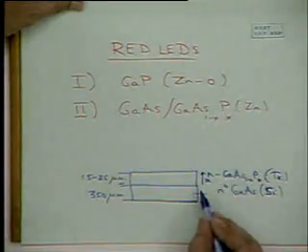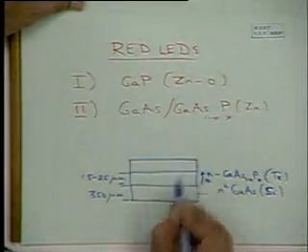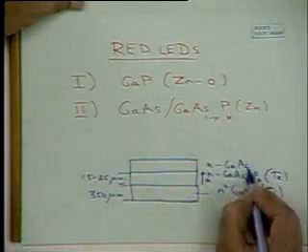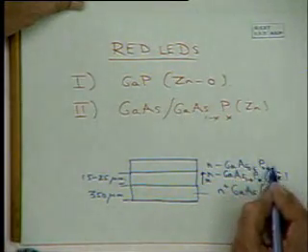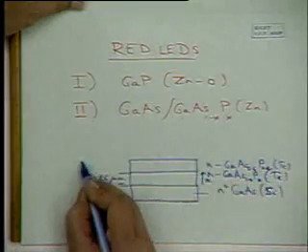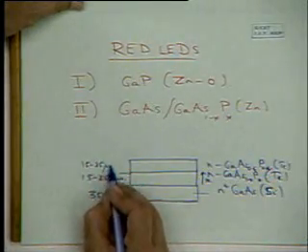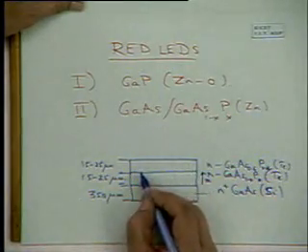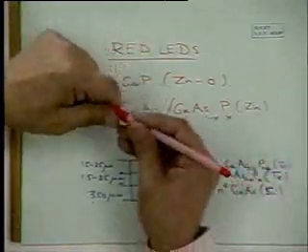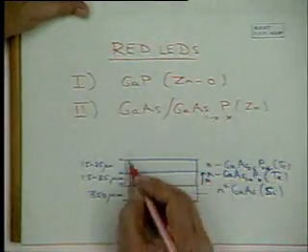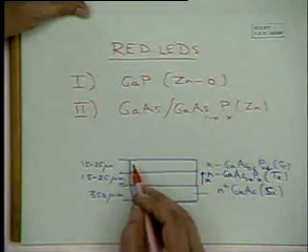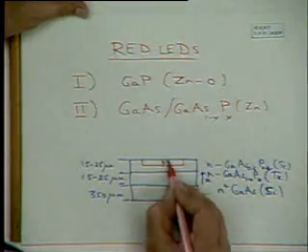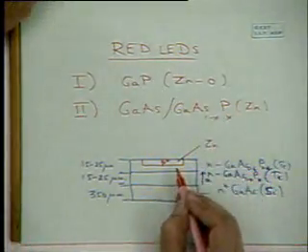So X increases until then you have a constant composition layer. This is N gallium arsenide 0.6, phosphorus 0.4. This is also 15 to 25 micron. This is the active layer. And in this, using silicon technology, using a mask, photolithography, etc., you diffuse a P plus layer, zinc doped.